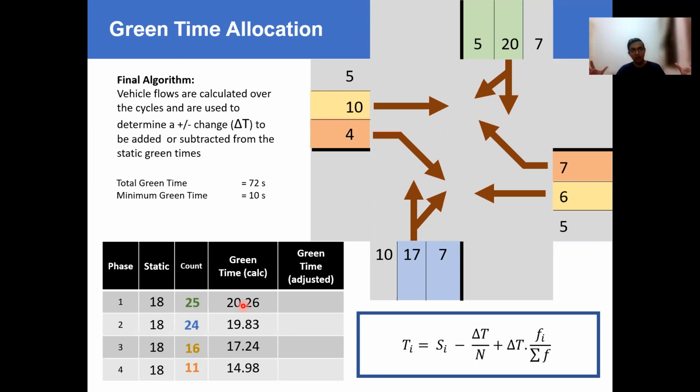If you combine all things, that is the cycle time. It's not going to change. All right. So there may be gaps if pedestrians are there, a little time, but overall, it can be 72 plus some seconds. Yeah. So this is how the system is developed step by step.